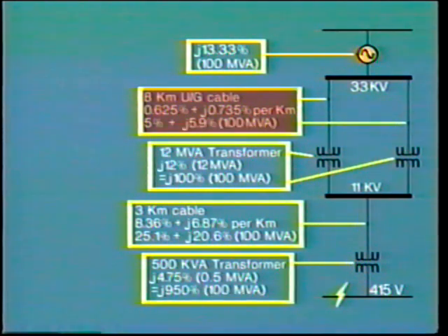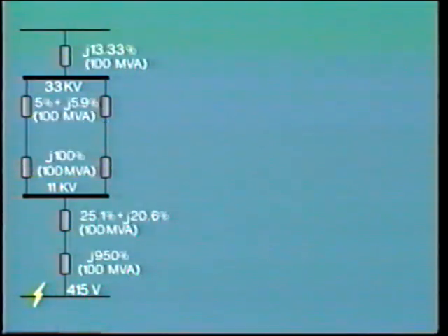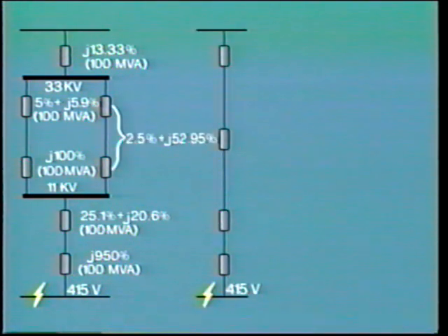The underground feeders and overhead line are both given resistive and reactive values. All of the respective R and X values must be added together. But note here we have a parallel circuit. Thus, in order to calculate the total impedance, we find it helps to draw an equivalent circuit. This is especially worthwhile when the system configuration is more complicated. In this simple example, we replace the parallel circuit with a single impedance and indicate the equivalent value.